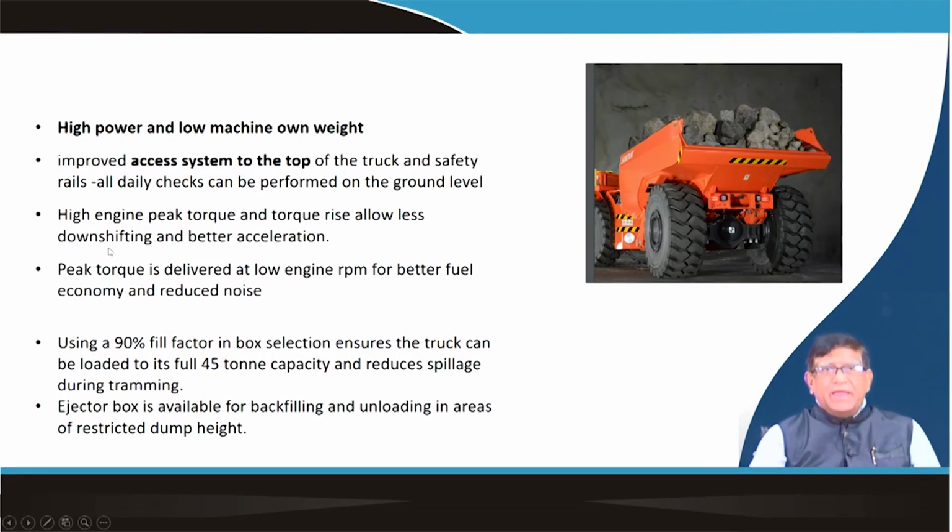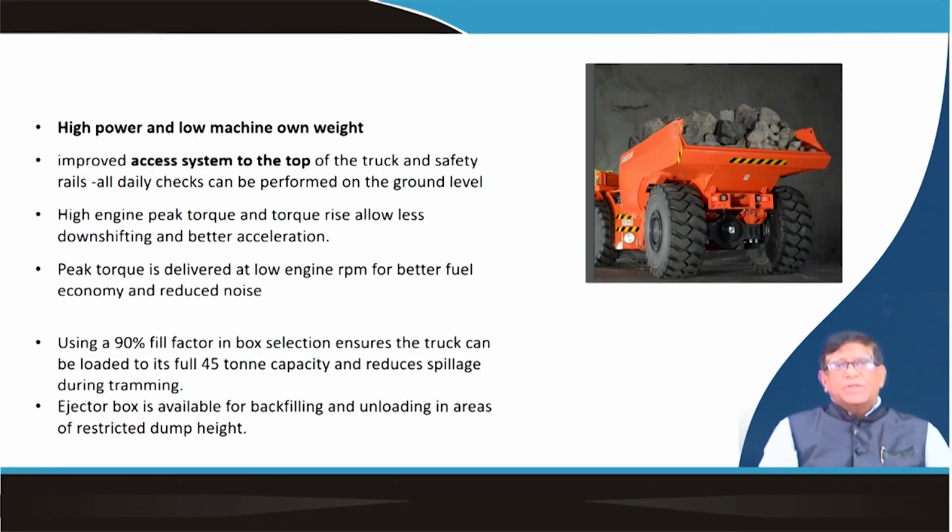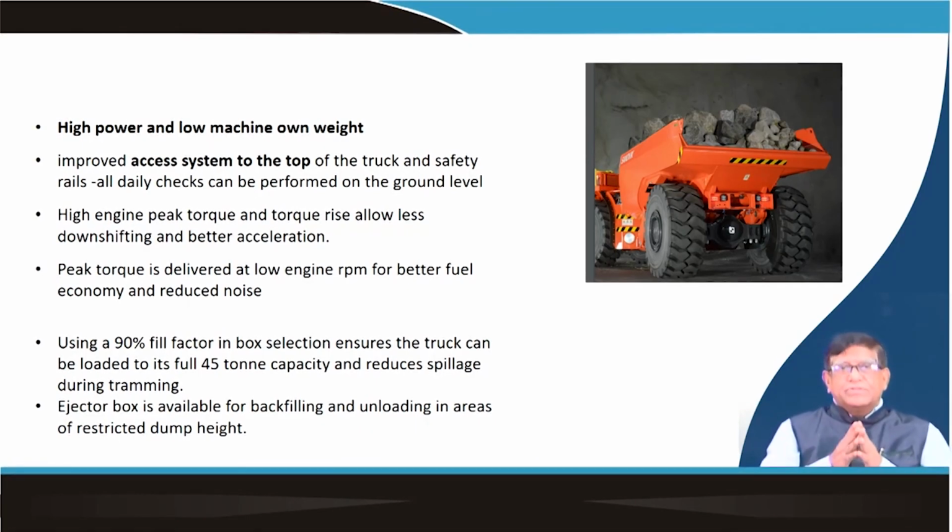Now, high engine peak torque and the torque rise allow less downshifting and better acceleration. This is an important feature, because the engine is now capable of providing the required additional torque when it has to negotiate a curve while driving at high speed.